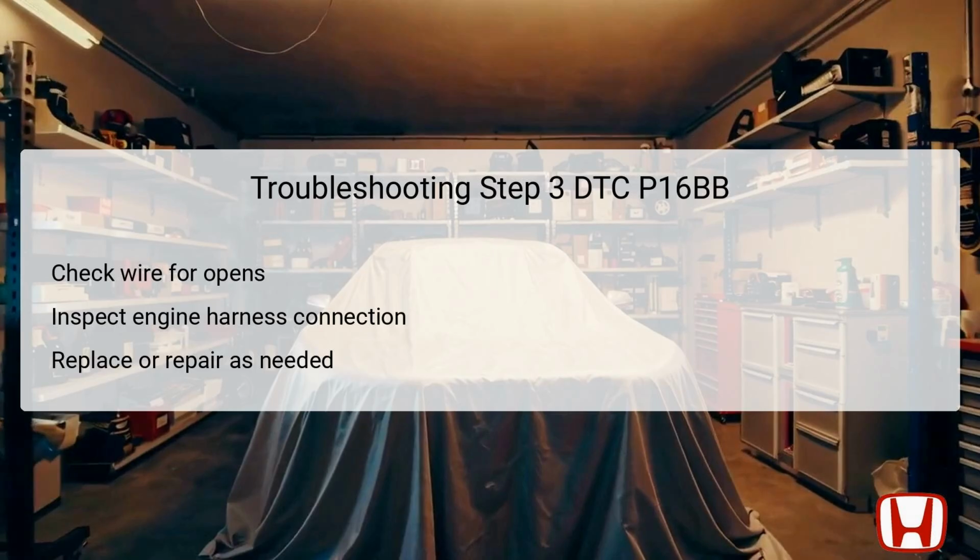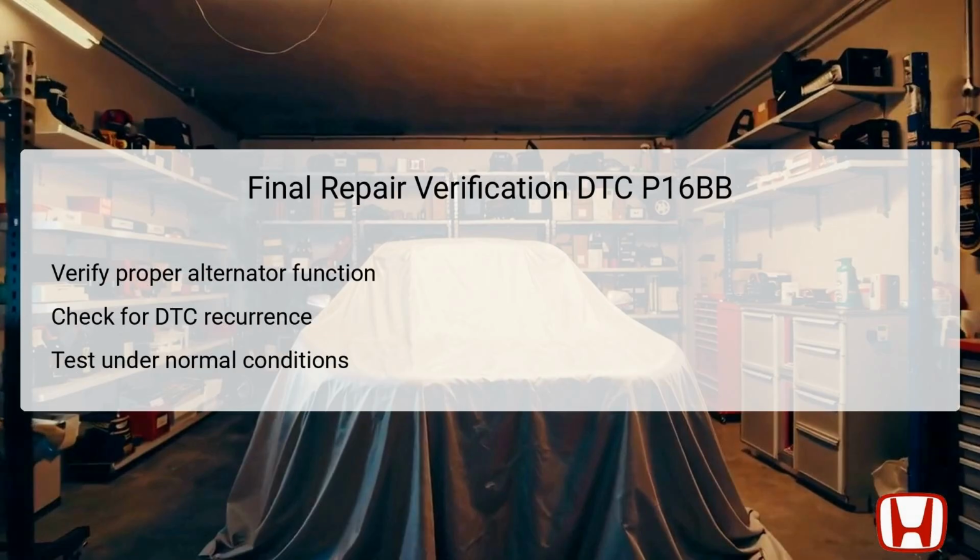Conversely, if an open in the wiring is detected, it necessitates repairs to restore continuity in the +B wire, ultimately ensuring that the alternator can provide adequate voltage to the vehicle's electrical systems. Following the troubleshooting steps and any necessary repairs, it's vital to verify that the alternator is functioning properly.